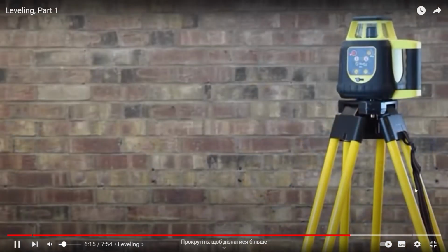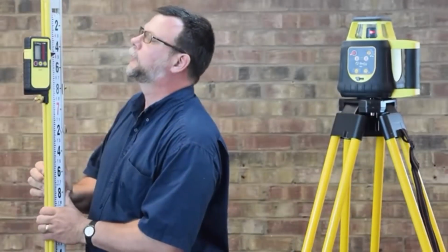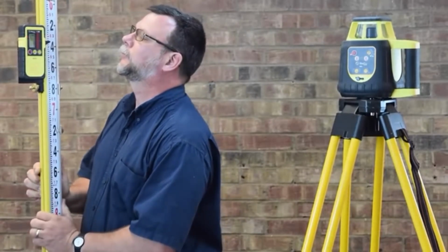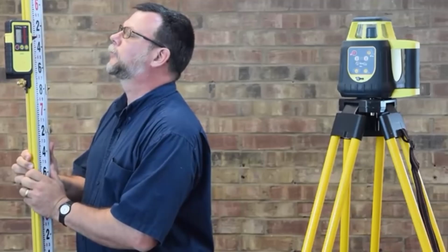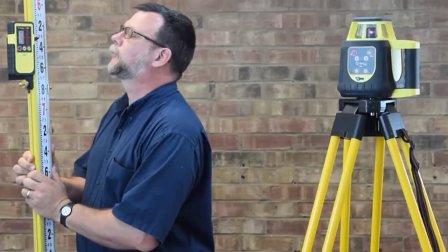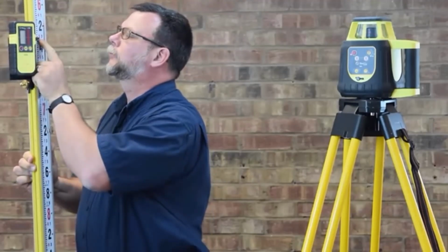With the advent of inexpensive laser devices, the rotary laser level has made some leveling surveys possible with only a single surveyor. A revolving mirror produces a horizontal plane of laser light. A laser detector on a special rod enables leveling measurement at each desired location.